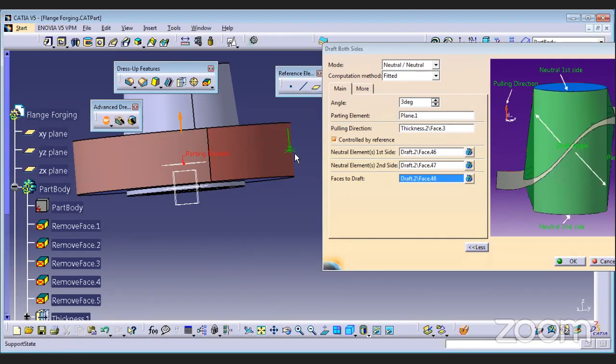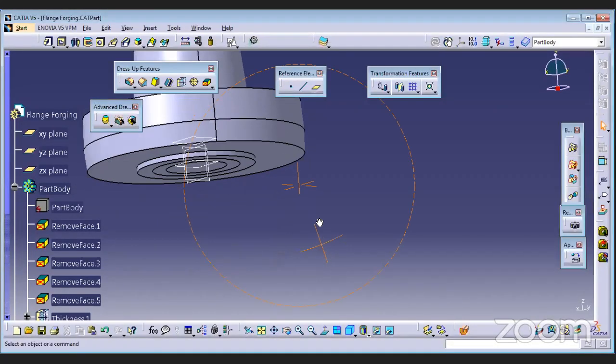So as per trigonometry, we can calculate these distances, but again it is hectic or laborious. We need to do calculations. But here there is an option fitted. So lower draft will be adjusted automatically using this option. So you can just say OK, say this draft.